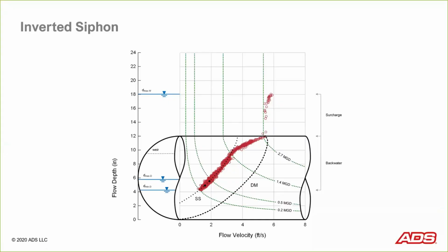So, again, that is a full siphon barrel because it's running below the grade line. If you do the math on there, that day in and day out, that siphon barrel is only running at 2.22 feet per second, which is below our 3.0 design guidance we would like to have. And what that tells me is this siphon probably has trouble from time to time with debris settling out in it, and it's probably a cleaning issue for this particular customer. So that's how you can take this technique, data from an upstream sewer, a little bit of knowledge about the downstream structure, and evaluate its performance.